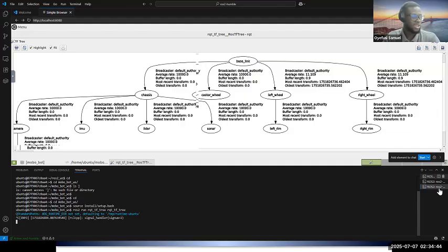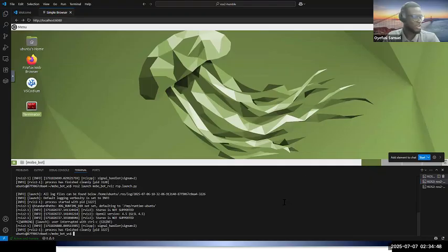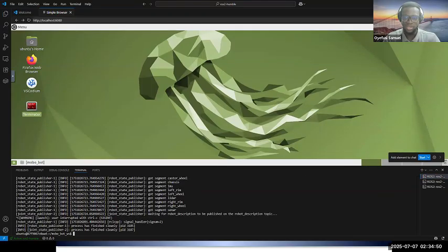All right, so let's close this and let's visualize our robot in Gazebo. I'm sure you're all excited to do that. So the next step now is to run our robot simulation. We made this package very user friendly. Once you run the Gazebo command, the robot sim launch Python script launches RViz and Gazebo at the same time. So when I run it, you see now.